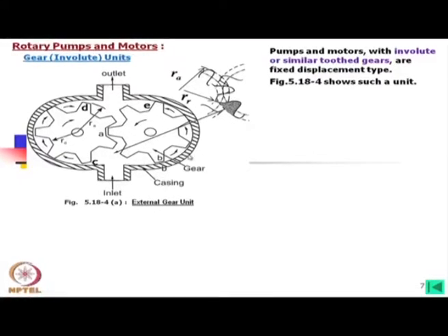For a 30-degree pressure angle, for 10 teeth not much correction is required, but for 20-degree, corrections are required. With those corrections, and also sometimes the tips are truncated or made longer, there will be a slight change from the pure or ideal involute profile.